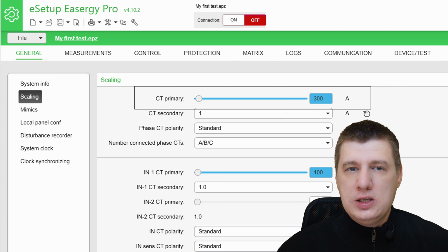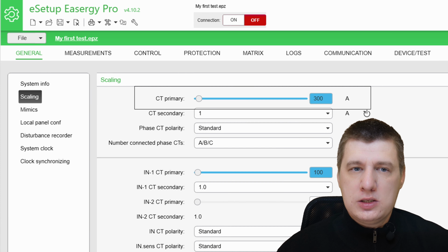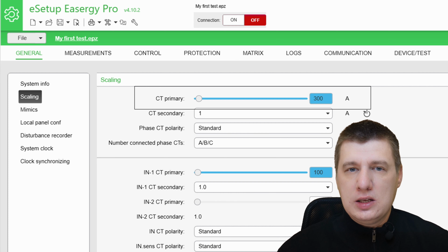The relay uses this ratio to perform internal math to convert the low-level signals received into primary network values. With the 300:1 ratio, the relay applies a multiplier of 300. If the relay detects a secondary current of 0.5 amps at this terminal, it calculates the primary current as 150.